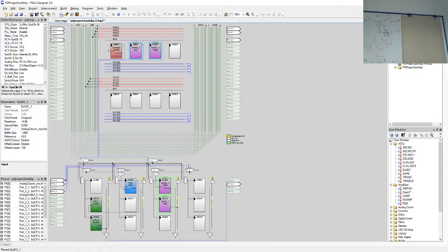Okay. Let's take a closer look at everything now, one by one. Okay, where did it go? So let's take the last piece that we put there: easy A to D converter, easy ADC. For routing the signal, we had to put that one here. So the input is actually coming from port 0 pin 3. That was the way to route the signal to this block.